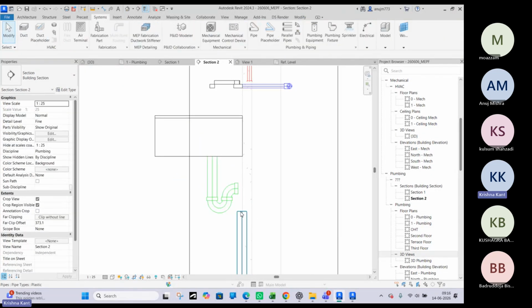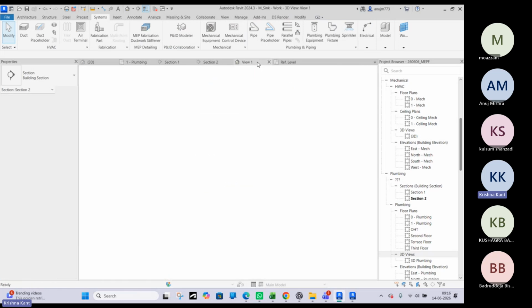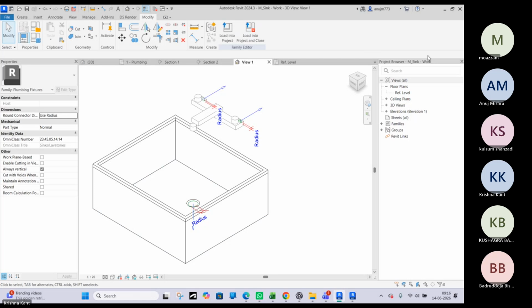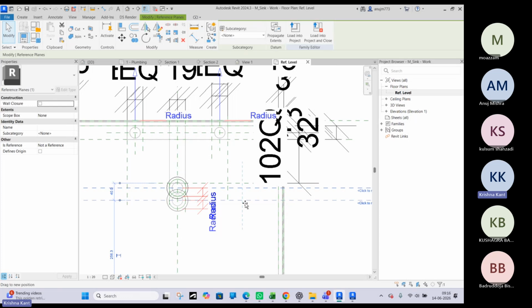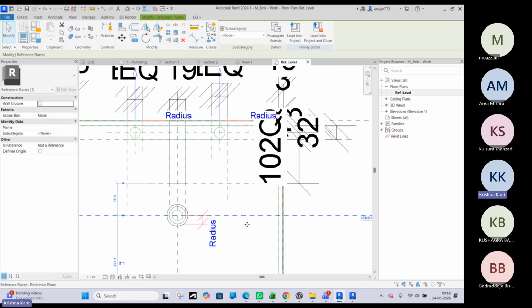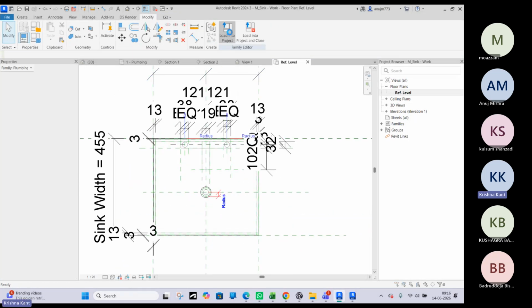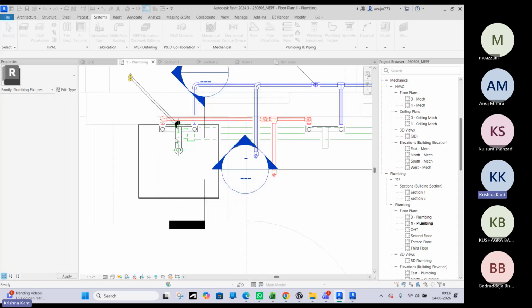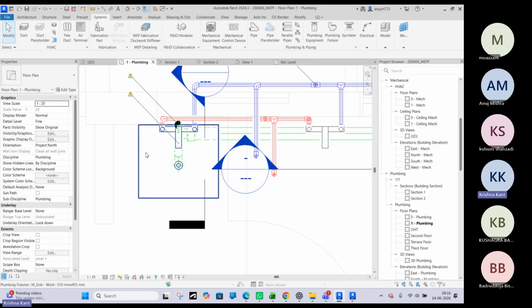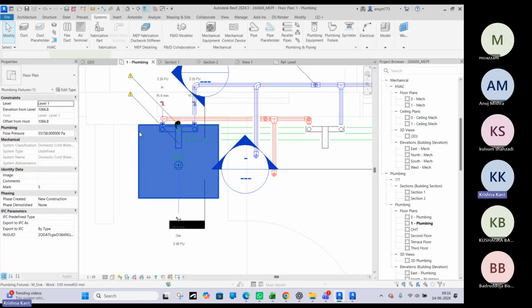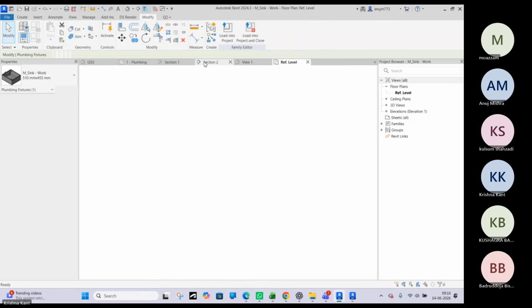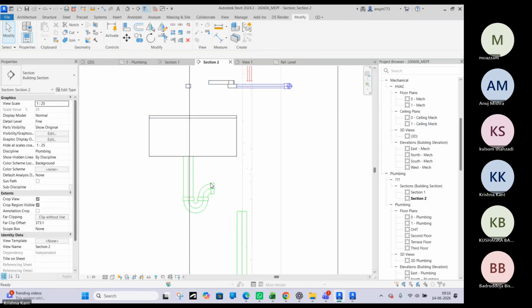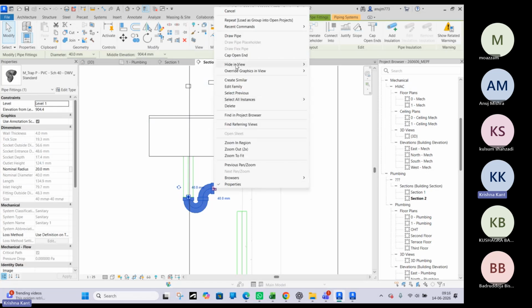So draw a pipe again. Now you can see we still require some space to bend our pipe. So that's why I bring the family radius point for this a little bit outside so that we will not have any issue to place. Or else we can provide the sink unit a little outside only so that we will have enough space for the P trap. Draw pipe.